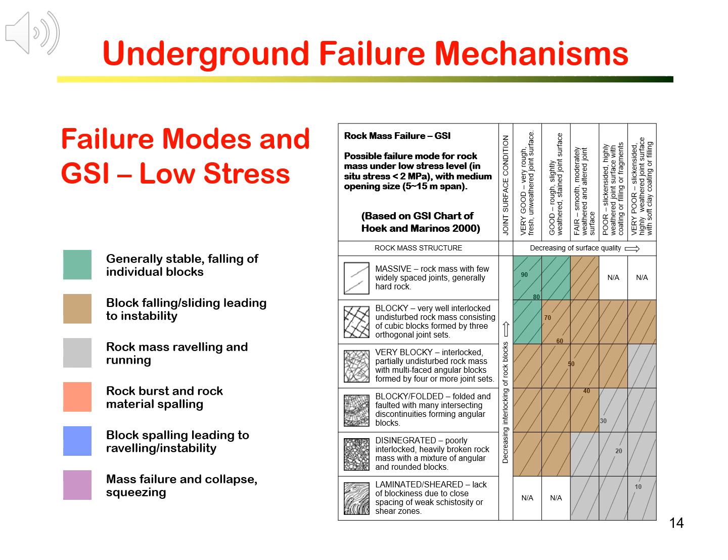The former occurs in blocky and reasonably fair quality rock mass, shown in mocha color. But for poor rock mass, we'll have general failure, indicated by gray. For high quality rock mass, we would expect stable excavation, which is in green.